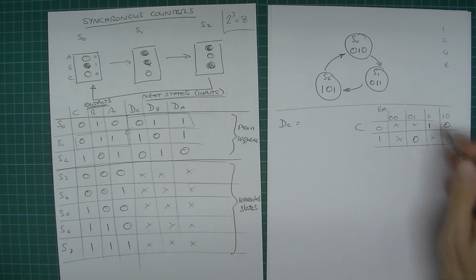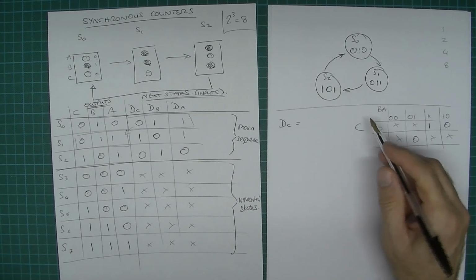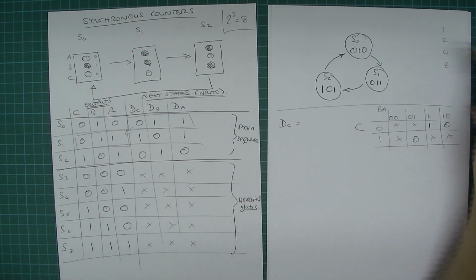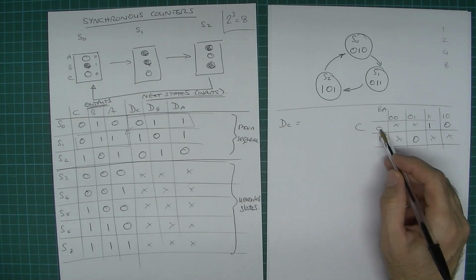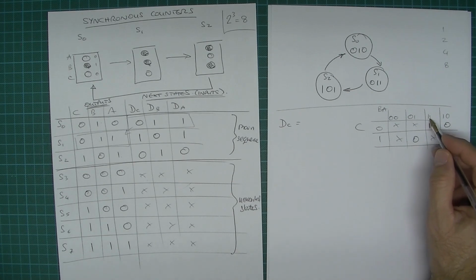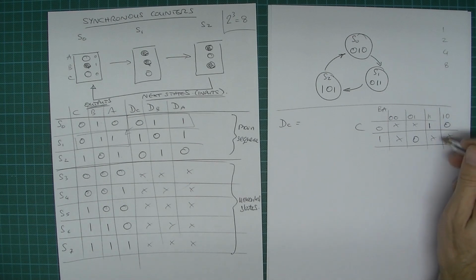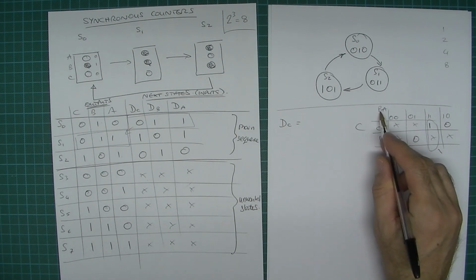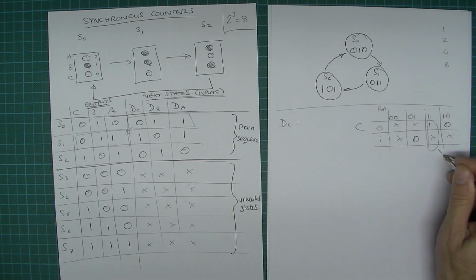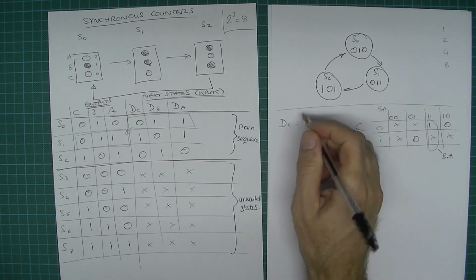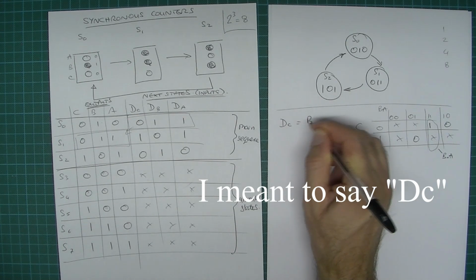So if, for example, you were to use this Karnaugh map and identify that there's only a group of 1, it would actually be not C and B and A, so it would be just a group of 1. However, you can make that simpler by saying, oh, I want that as a group of 2 because this one is a don't care, so I can make that into a 1. So that makes that group actually simpler, because now that's going to be B and A. Remember, BA, that's BA. So we can now say that DC equals B and A.